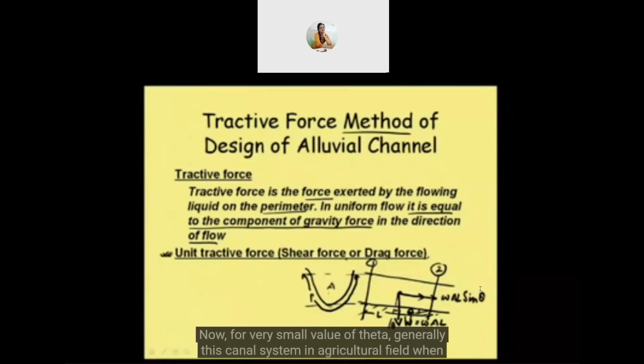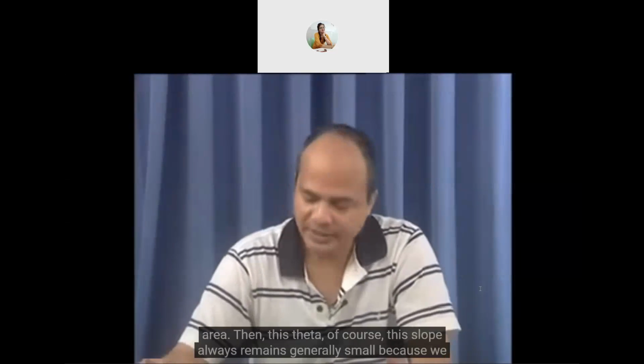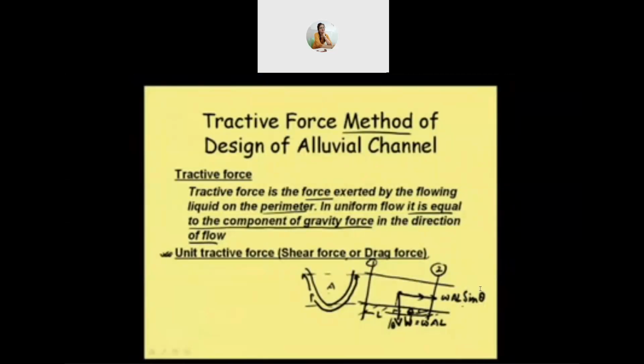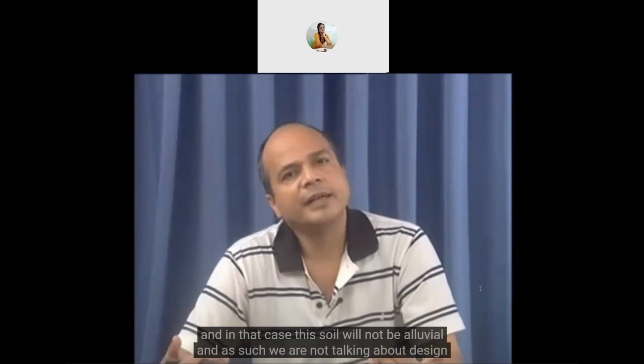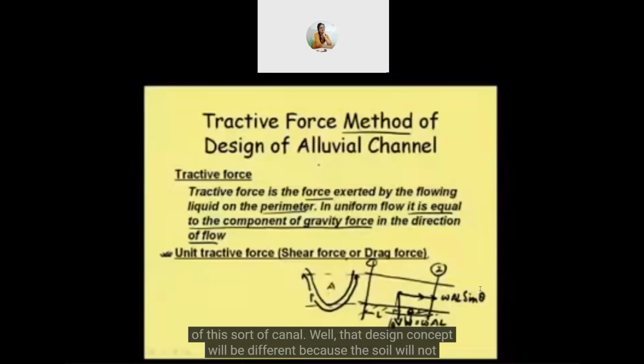Now, for a very small value of theta, generally in canal systems in agricultural fields, when we design, these are normally not having a very steep slope when we talk about plain area. This slope generally remains small, because we are doing the design of alluvial channel. Alluvial channel will normally be in the river valley, and the slope will not be very high. But if we talk about agriculture in hills, the soil will not be alluvial, and we are not talking about design of this sort of canal. That design concept will be different.